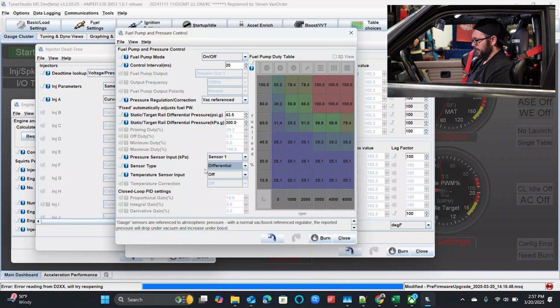Just to cover it, an absolute sensor means that it is scaled off of the closest we can get to a perfect vacuum on planet Earth. It's impossible to get to a perfect vacuum inside an atmosphere, but they do pretty well. What this means is that your absolute pressure sensor will read somewhere around barometric pressure when you have no pressure on the rail.